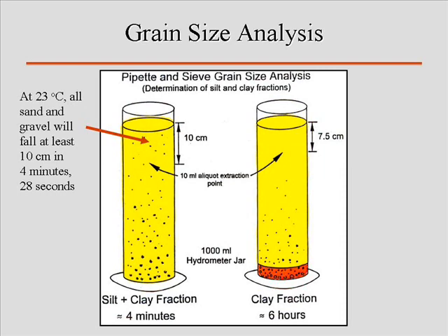So Mary, when we were doing yours yesterday, that was 21 degrees, it was 4 minutes 48, right? A simple matter, we did some stuff for Mary the other day. At 20 degrees Celsius, it was 4 minutes and 48 seconds. You lost 20 seconds. You already had to wait 20 more seconds for the finer sands to fall down. The warmer it is, the less dense it gets.